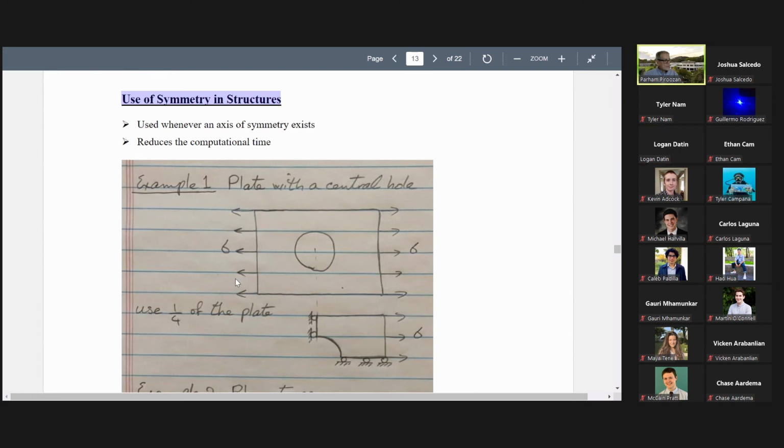Oh, if you want to remove, for example, the stress here, we can't do that because we are using the symmetry of the geometry. If I remove this stress, then the whole geometry is still here. I have to use symmetry in the geometry to reduce the size of the problem. For analysis purposes, of course, I cannot use sigma here.